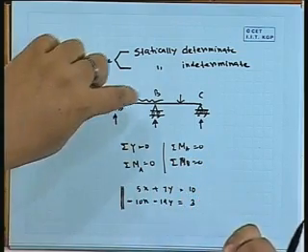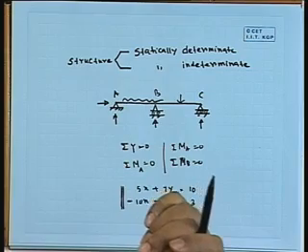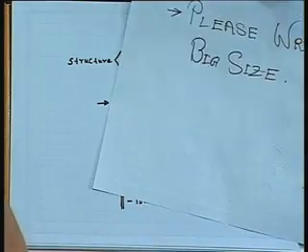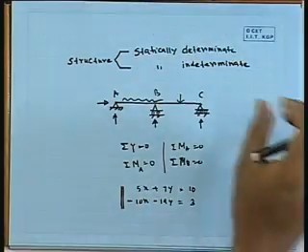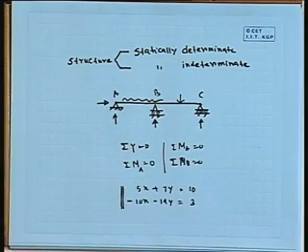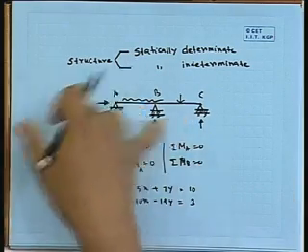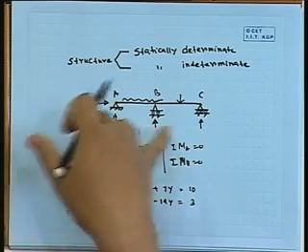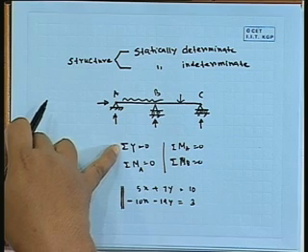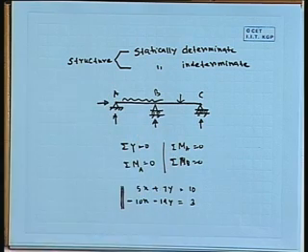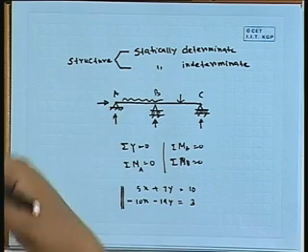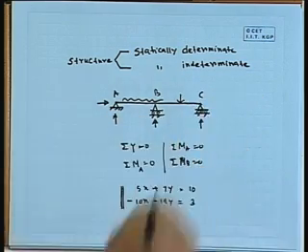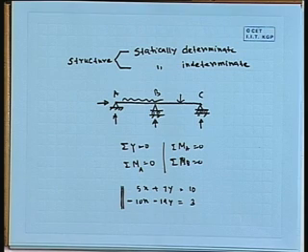Now, this problem which is drawn here has basically 3 reactions, and we can take equations in this form or that form. The third reaction we can't find out because the total number is more. Now, how can the problem be solved? The problem can be solved if, in addition to those equations, we require some other equation.